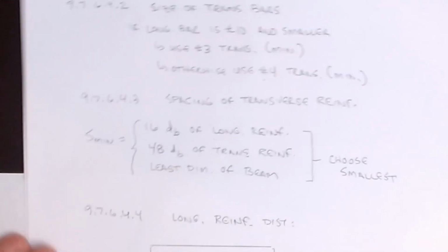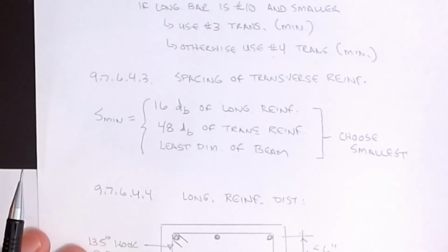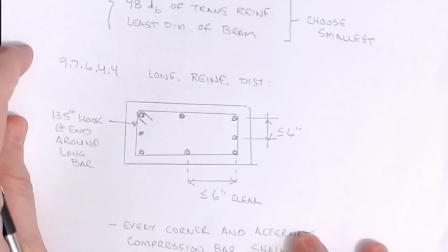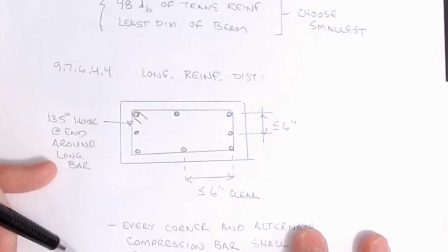The last requirement, and where we'll end our discussion, has to do with the distribution of the reinforcement around a cross section, and in particular with regard to bars in compression. This is the same game as compression reinforcement in columns, but it also works for torsion.